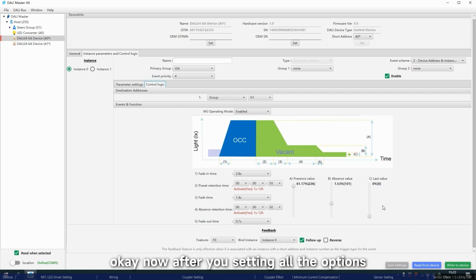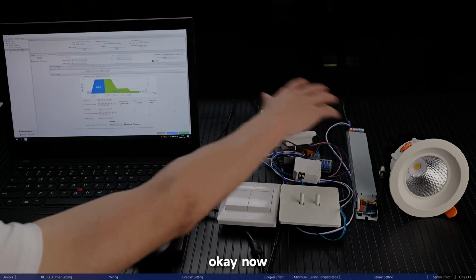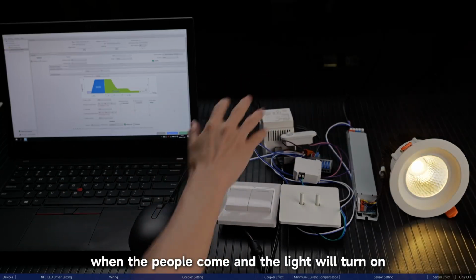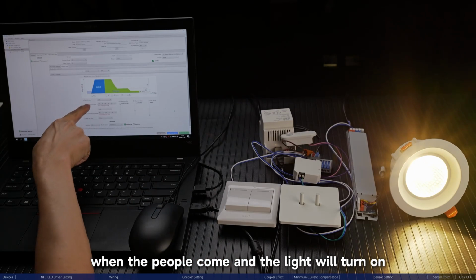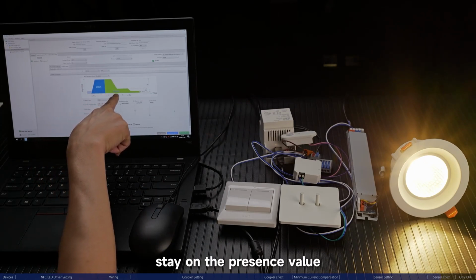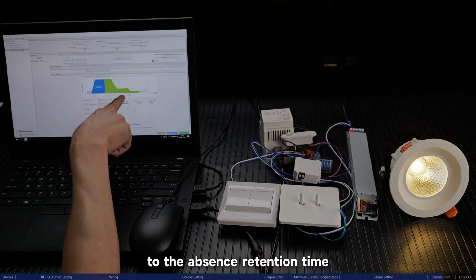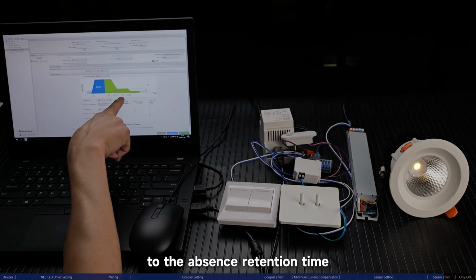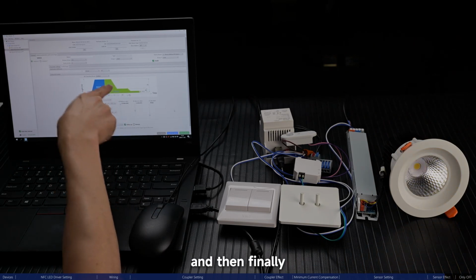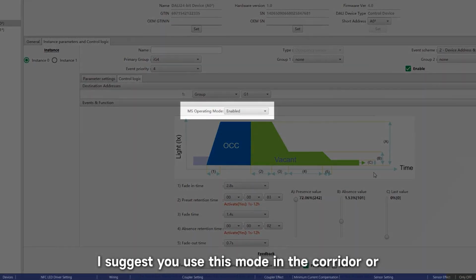Okay, now after you set all the options, we click write to device. Now when people come, the light will turn on, wait in time, and when no motion is detected, stay on the presence variable, and then fade to the absence retention time, and then finally fade out, turning off the light. I suggest you use this mode in the corridor or staircase.